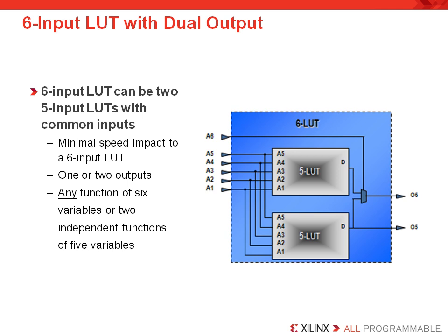Also keep in mind that if you're trying to design at the maximum speed quoted in the device datasheet, you have to remember to limit all of your delay paths to one LUT or one logic level. This is not typical, but some customers do it by extensively using pipelining and by minimizing their combinatorial logic. The Designing for Performance course discusses pipelining.